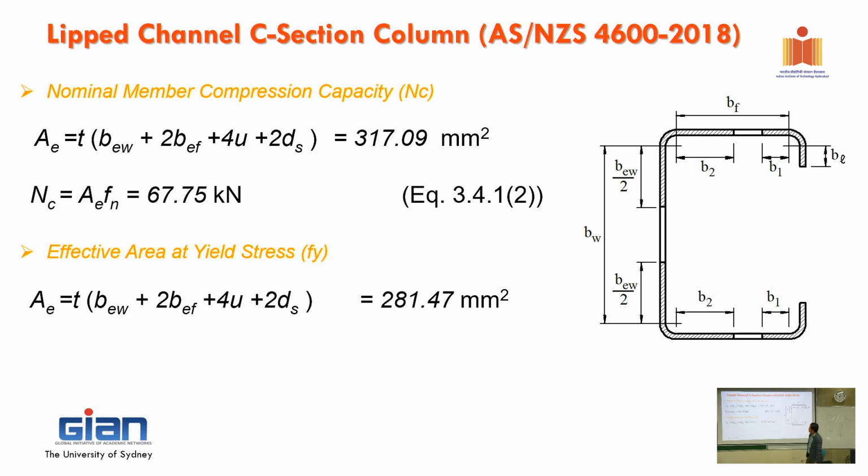And some students I taught, they do this one and they're happy and they plug into the equation and that's it, done. But it's not right. You have to calculate the capacity at the critical stress, not at the maximum stress. But in our equations for columns, there are always two. One is section capacity, Ns. Yes, you have to calculate exactly the same process with M star equal to My, as F star equal to Fy.